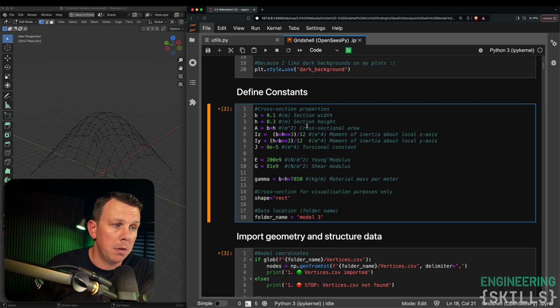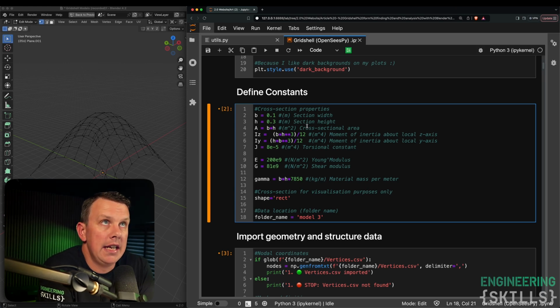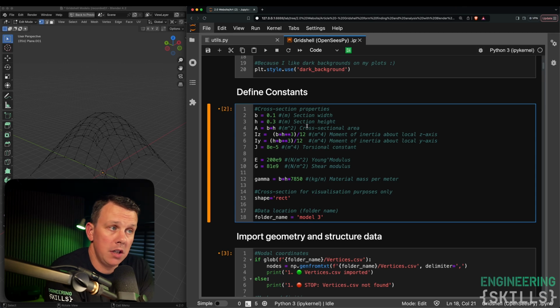They don't resist moment. And what you'll find if you try and do that is that the stiffness matrix for the structure becomes singular. And what that really means, the physical manifestation of that, is that you have rigid body motion within your structure. Really what this all boils down to is, in theory, when you invert your hanging chain, you should get a structure in equilibrium in a state of compression. But the problem when you go from tension to compression is that your equilibrium, which was a stable equilibrium in tension, becomes an unstable equilibrium in compression. And that means essentially you can't solve that structure using a truss model.